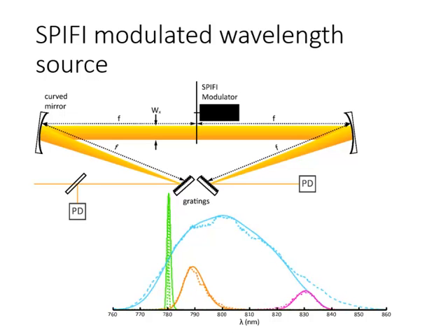So now we've converted wavelength information to spatial information, and then we can use this modulation imaging system to convert that spatial information ultimately into electronic frequency. And we can make a hyperspectral imaging source, or in the very simplest case where you just collect the modulated beam, we've created a spectrometer.